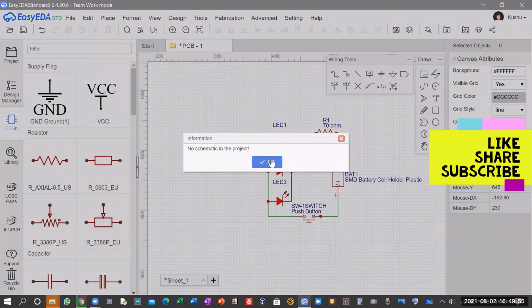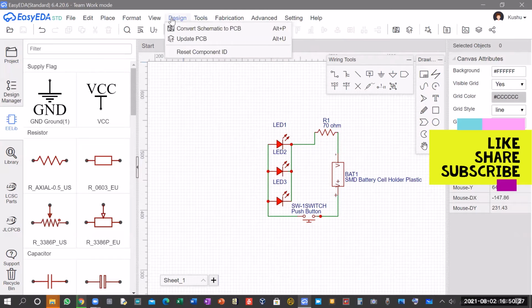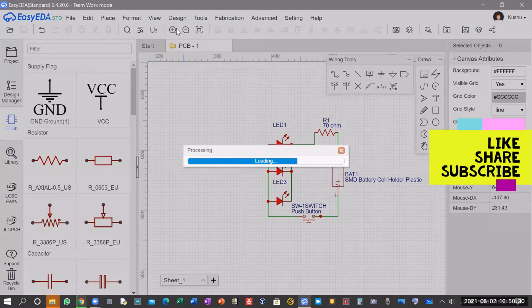No schematic in this project. Oh, okay. So that can be caused when you don't save it. So yeah, save it first. Connecting to server, and you will see that your project has been saved successfully. After you have done that, go to Design, Convert Schematic to PCB.